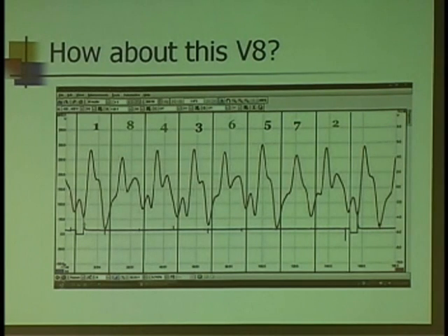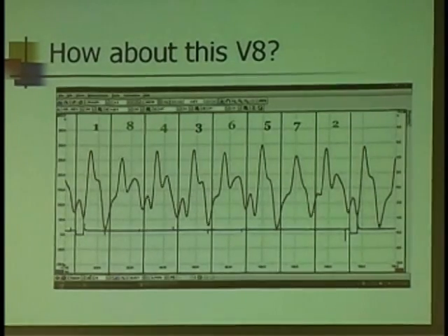But where am I attached to the fuel rail? It really depends on where the Schrader connection is. Will there be some dampening of the pulse as it's moving further away from the point of pickup? Just like a manifold vacuum gauge. The closer I get to the source of manifold vacuum, the better reading I'm going to get with the tool, right? So it's the same thing with this. And you take that into consideration.